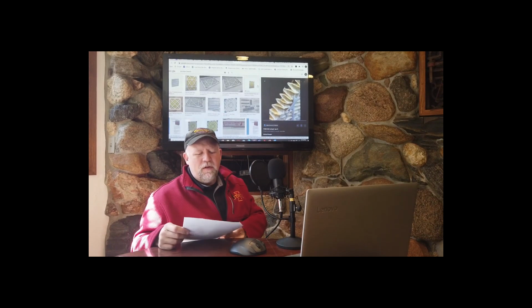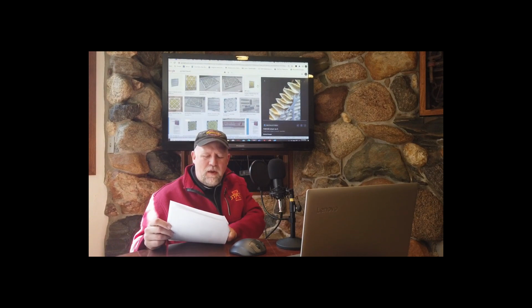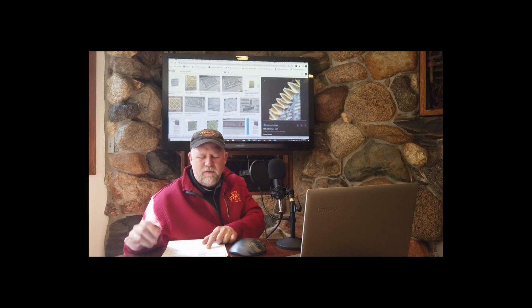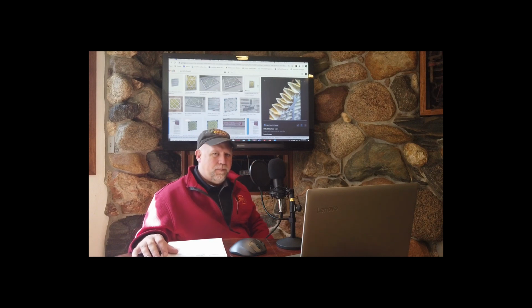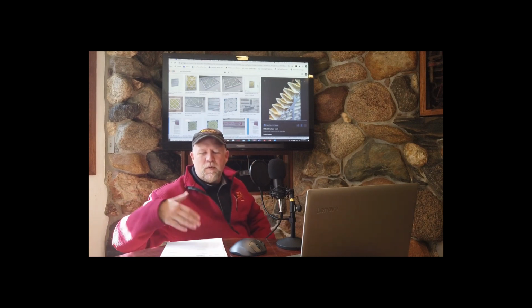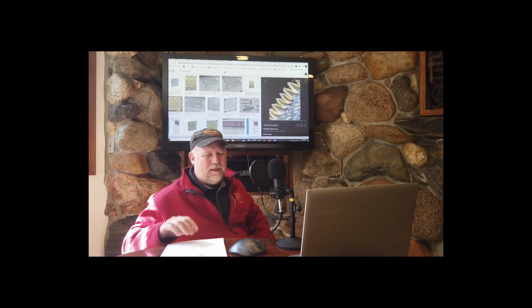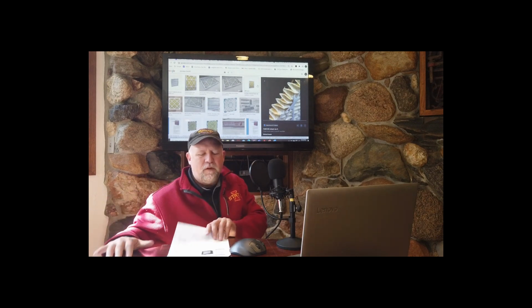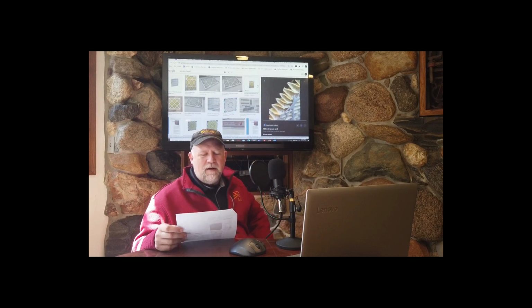All right. So these are MERV 8 filters. Pretty good. But notice the price. For a 12-inch by 12-inch size, that's 1 square foot of filter on MERV 8, we can buy 6 of them for almost $6. So the cheap blue ones were 10 cents a square foot, and now these are more like $1 a square foot. Order of magnitude, 10 times more expensive. All right, but let's keep on going. Let's go to an even better filter, right? Once again, if we look at the Purolator Dominator high efficiency filter.